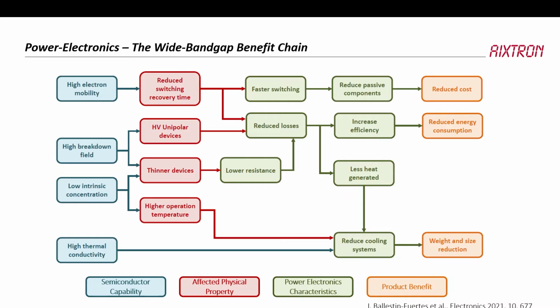So you're actually ending up with a smaller, more compact device, or more compact circuit. And at the same time, the amount of raw materials that you put in, and this goes into the question of green tech and all these things, becomes a bit more favorable when you can use a higher switching frequency. So that can reduce the cost just as well as reduce the amount of materials that go into these circuits.